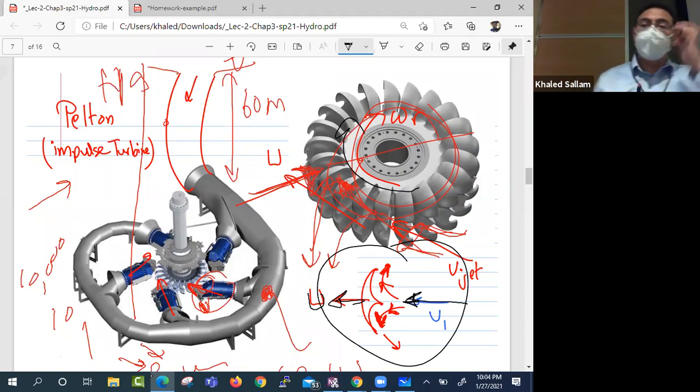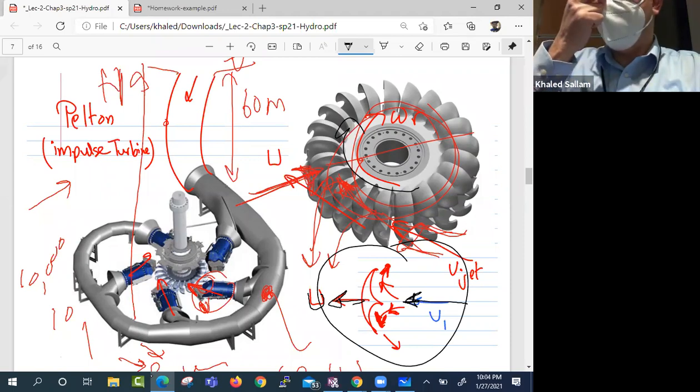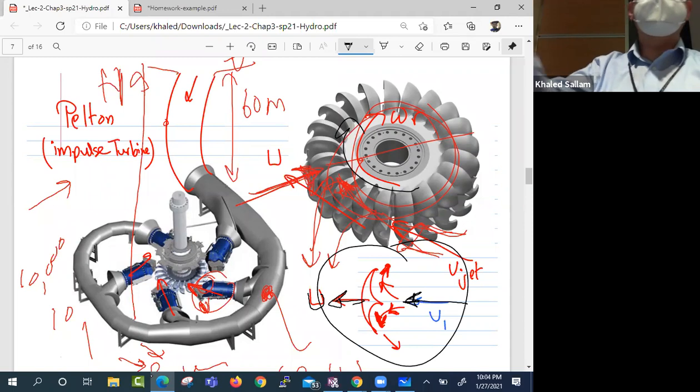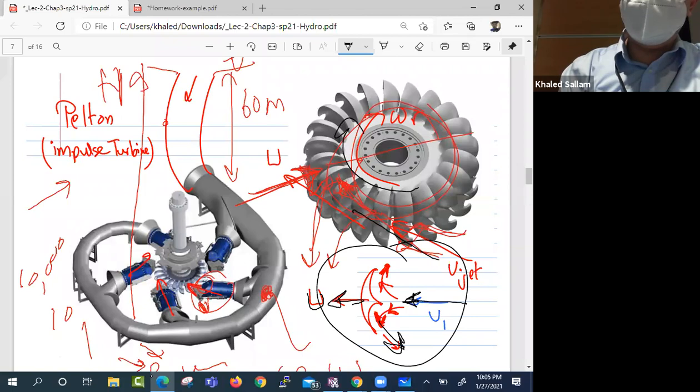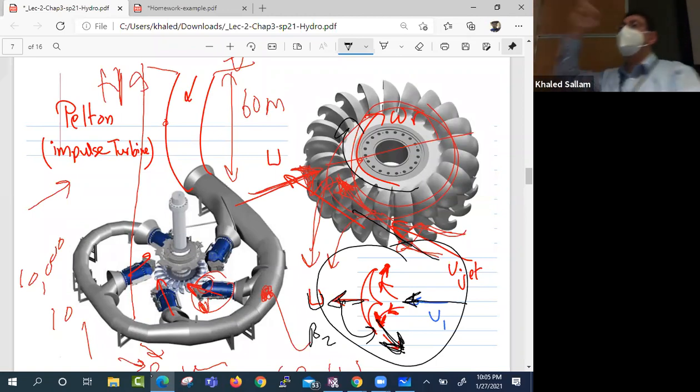So likewise, does it have any relation with the angle? Which angle? Beta 2? Which angle is strike? So alpha 1 is always 0 because he shoots axially. I mean, he shoots with the plate. But the angle at leaving, that beta 2, ideally you want it to be... if I hit you with this and it bounces back toward me, that will hurt like hell.